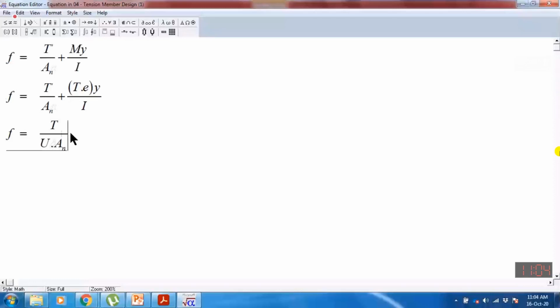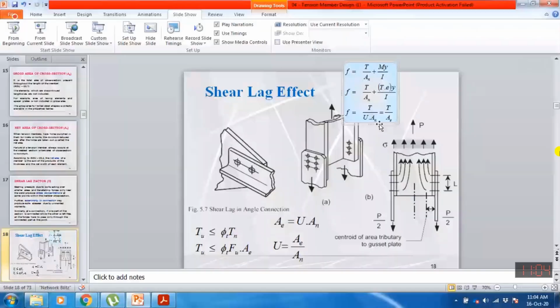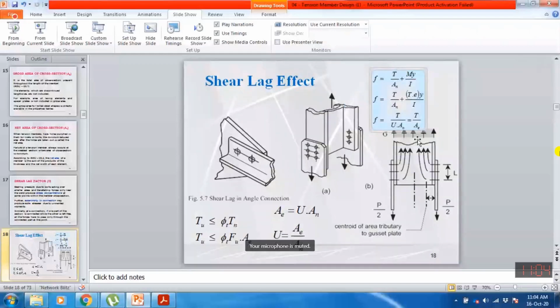So due to two reasons. Number one reason is due to the eccentricity. This area will be referred to as the effective area, which means that if I'm reducing the area, stresses are increased. So I'm increasing the applied stresses due to this moment case. So this is one, due to the eccentricity. And the other will be the stress concentration. Stress concentration means, what is stress concentration? Actually,